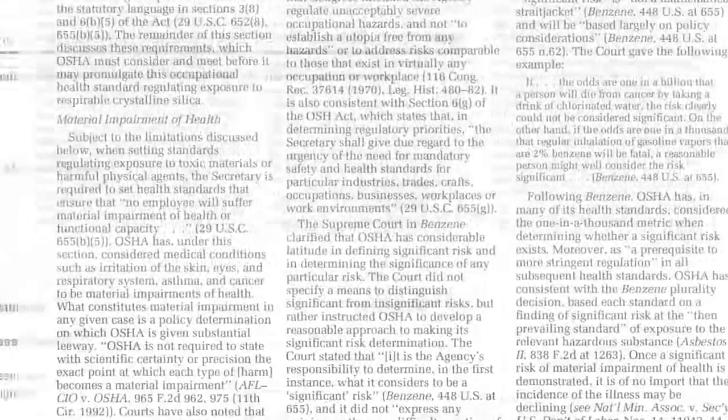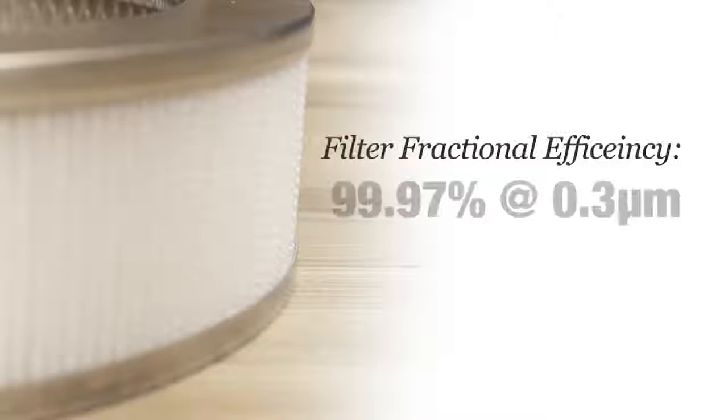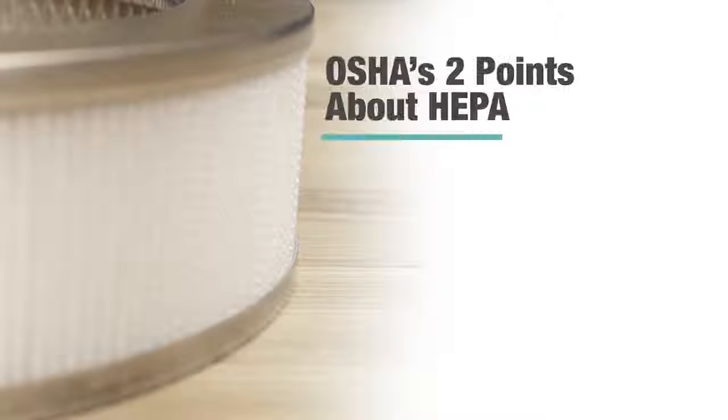Let's first take a look at what is written about filter efficiency. It shows us that OSHA had originally considered requiring HEPA filters, which provide a filter efficiency of 99.97% at 0.3 microns, because they believed they offered better protection from silica dust. However, they found two things.